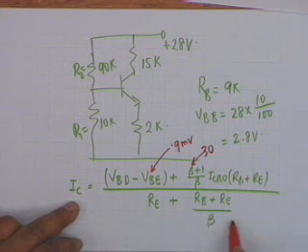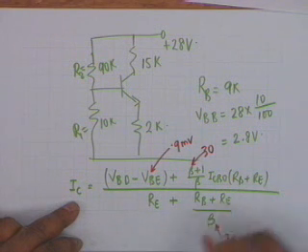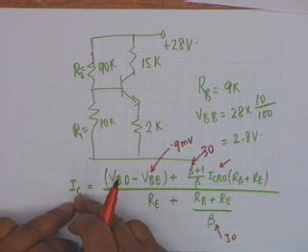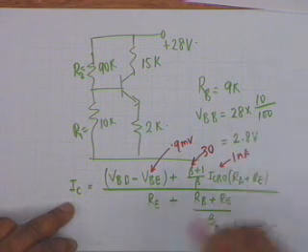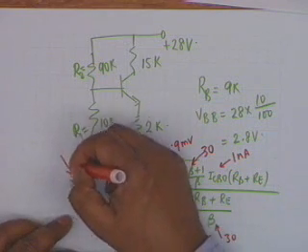So you put beta equal to 30, and for ICBO put the lowest value, that will give you the lowest IC. Is that okay? Lowest value is 1 nanoampere. You put down these values, then I sub C comes as 0.8 milliampere.